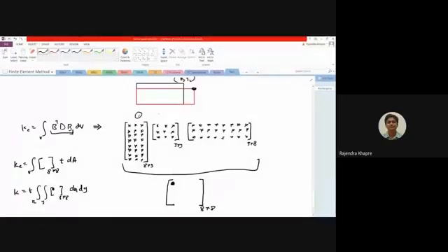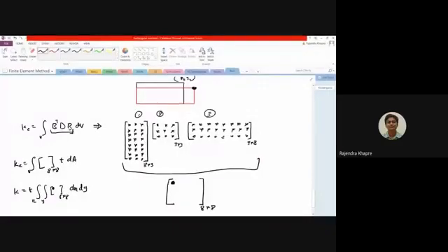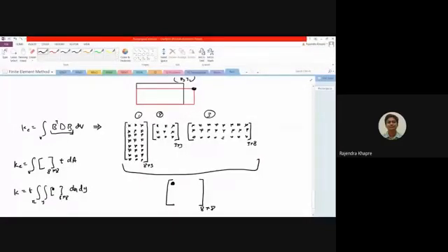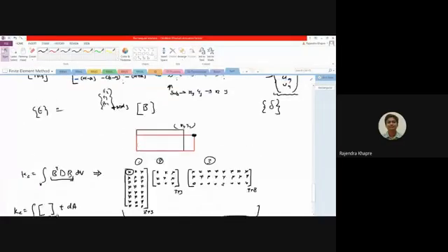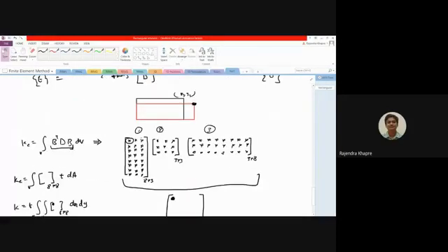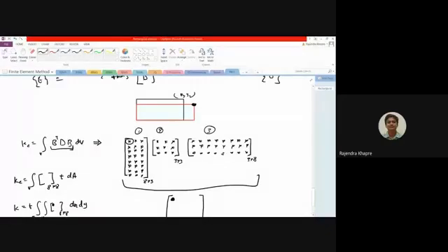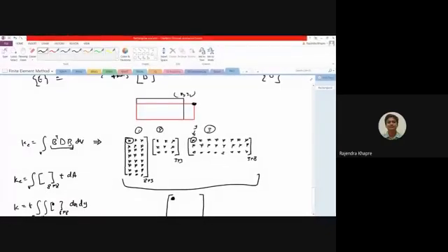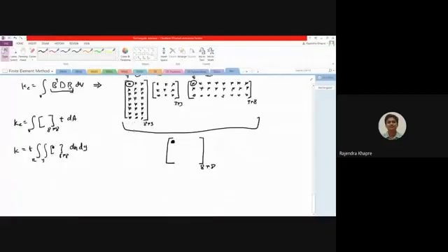This is matrix number 1, matrix number 2 and matrix number 3. Remember this term, that is the B1 term. Okay, so the B1 term has an equation something like B minus y. So it is now depending on the value of y. So this is also depending on y, and this is also depending on y. So what you will have to do is integrate all 8 by 8, that is 64 terms, for dx as well as for dy.